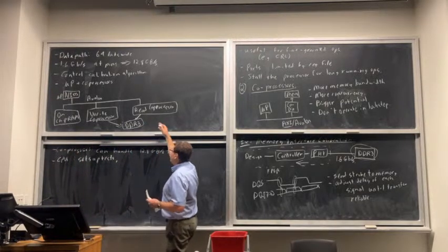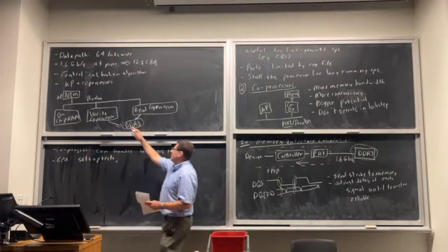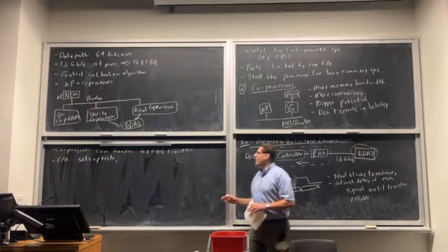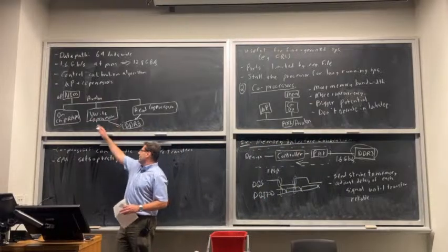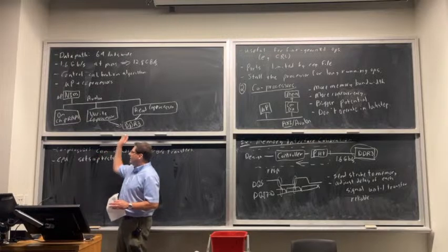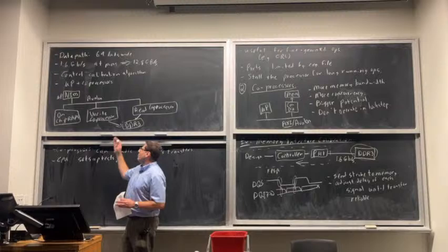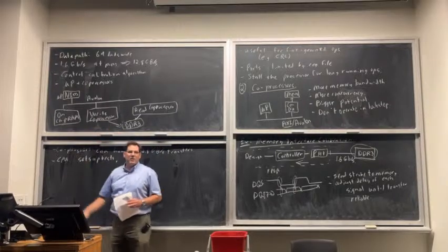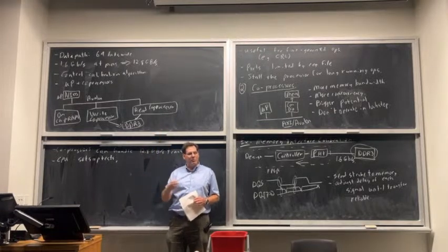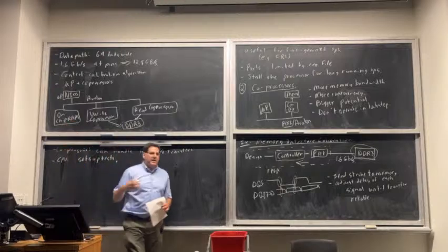And these read and write coprocessors stick the data back in this on-chip memory. So the Nios processor might set up a block of data in the on-chip memory and send it to the write coprocessor: starting at this on-chip memory address, I want you to send 128 bytes of data to the off-chip DDR at this address. And it does it, and it'll write back the data that it reads. Then you can send a command to the read coprocessor saying, now read from those addresses and stick the result back here. And then the Nios can look at it, right?